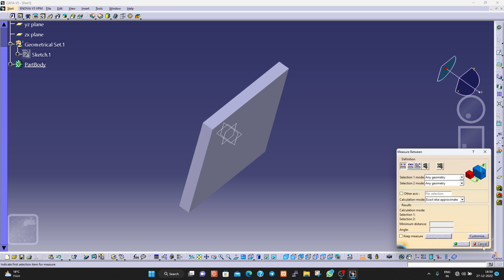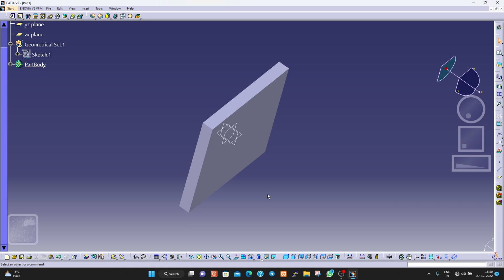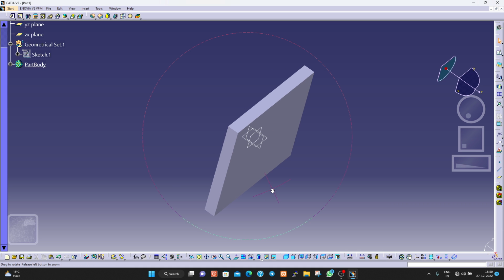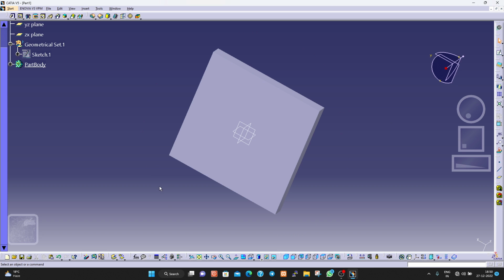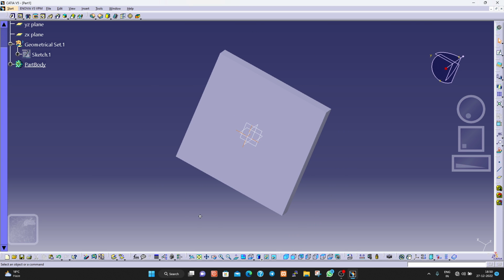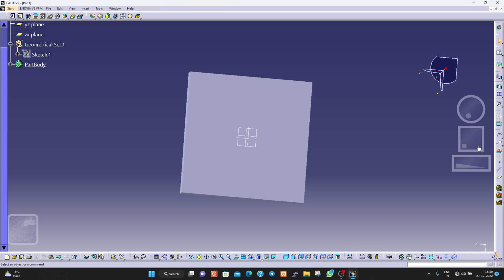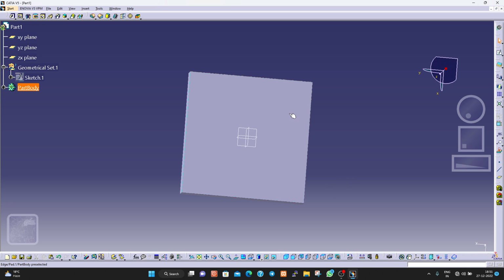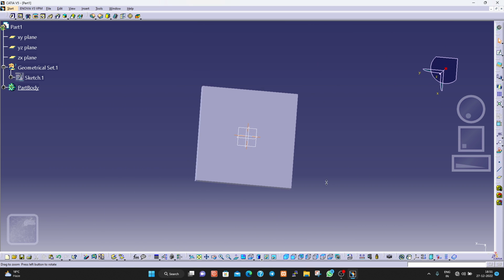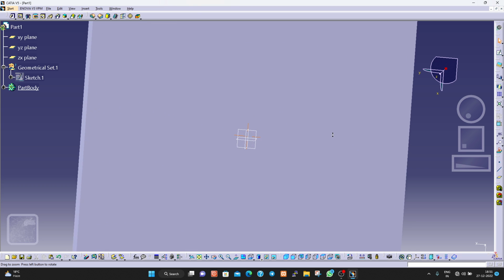Okay, and one thing I forgot to tell in the last video was that we do not need these three, we can go with our mouse too. For zoom in and zoom out, we will just press the middle mouse button once, click the right key and drag up or down: down for zoom out, up for zoom in.